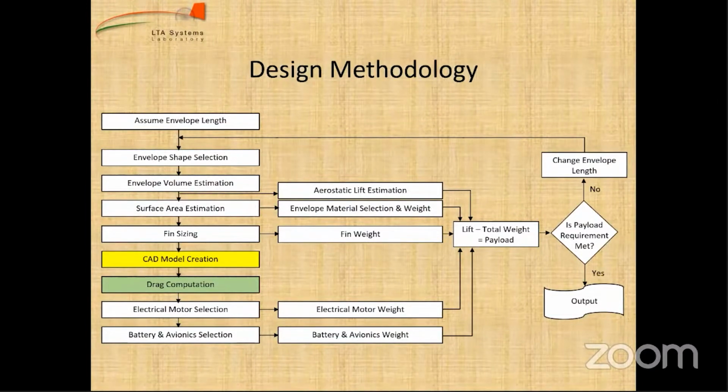It's a very complicated technique because you have to make a CAD model. Then if you put all these fins and all, the grid size becomes very accurate, and you need a lot of computational resources to estimate our drag, which will make this conceptual design process a little bit complex. So in this tutorial, we will be looking at a simple empirical formula to estimate the drag of a given airship. Using that empirical relationship, we'll estimate the drag.